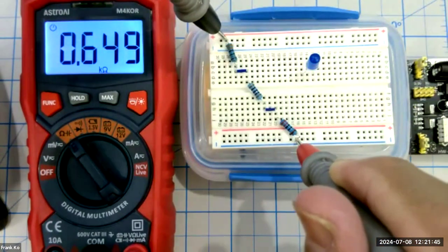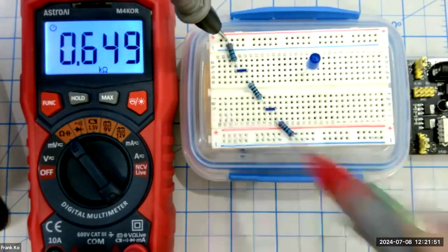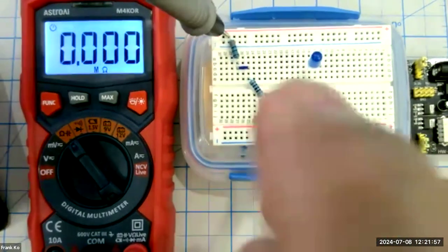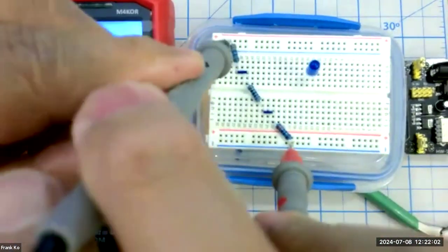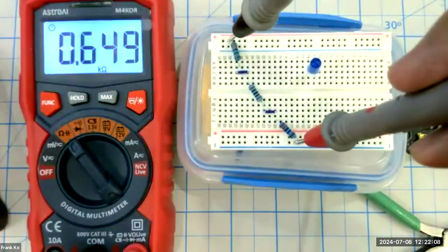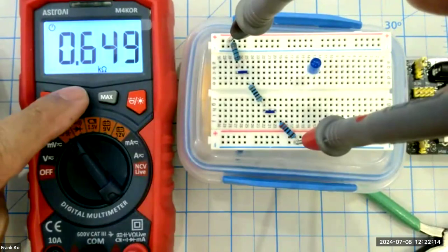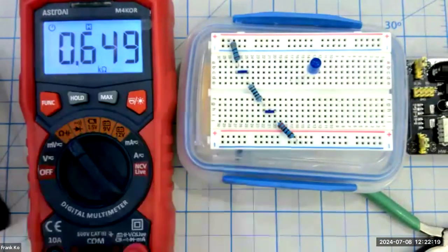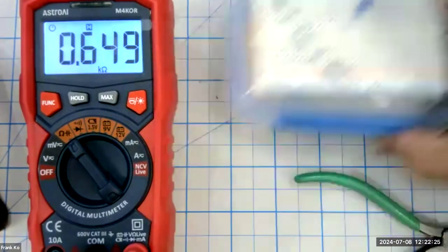And very simply, let me just go ahead and show you this. Let's see, our reading was 0.649. Since I'm using two hands, I can put the two hands into one, kind of like so. I'm trying my best to do this without blocking the camera. Maybe I'll do it this way. All right. So 0.649, and I'm holding this with the right hand. And with the left hand, I can just press hold, the little H, and it'll hold the display. Now I can take my probes off, and I can verify this number separately. So what I'm going to do is grab the handy dandy calculator.